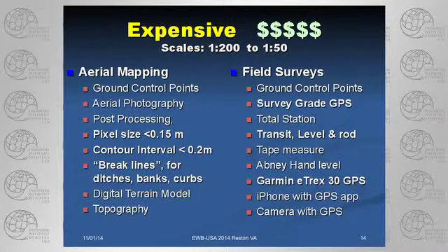Probably the most expensive way to go is aerial mapping. If you look at the previous slide, it said uncontrolled at the bottom of the slide. What uncontrolled means is that's just the elevation the satellite thinks the ground is, so it hasn't been ground truthed to the real accuracy of the ground. If you want a more accurate model, you have to drape those elevations and that imagery to what the true coordinates are on the ground and the true elevation at specific points.